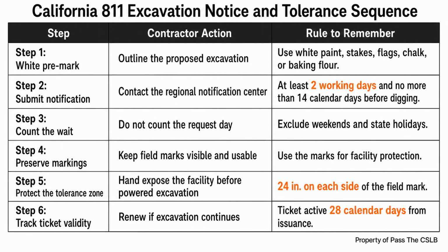Measure 3 feet along one line, 4 feet along the perpendicular line, and check the distance between those two marks. When that diagonal is 5 feet, the corner is square. Larger multiples can improve the usefulness of the check on a larger layout, but the same proportion remains. The method confirms a right angle. It does not establish the legal location of the building. A perfectly square foundation can still be perfectly wrong if it was squared from the wrong control. That is why geometry comes after verified survey control, not instead of it.